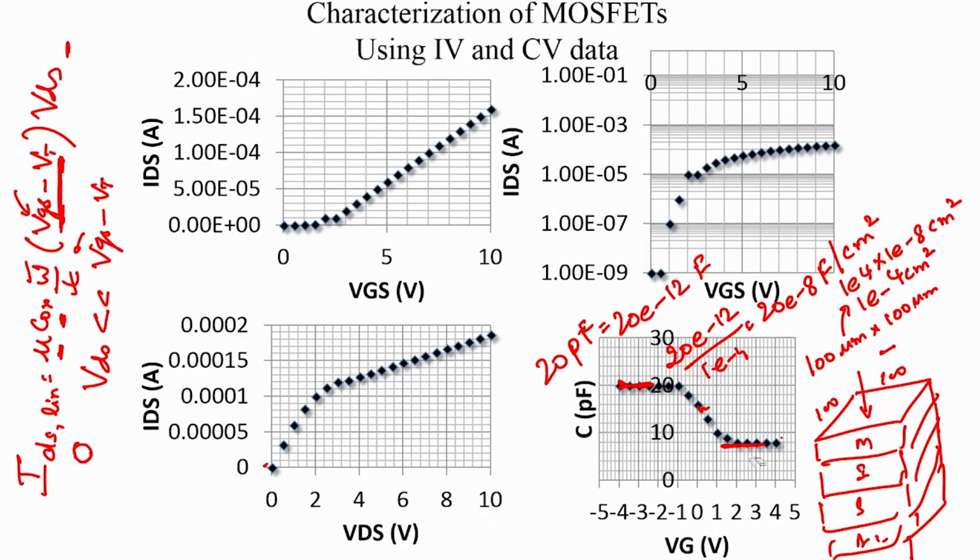Okay. So do forgive me if I am making typos here, but I think it is right. So this is about 200 nanofarads. So I think when we had the discussion on CV measurement earlier, I made a mistake. It was one order lesser, but what this tells you is Cox is 200 nanofarad per centimeter square. So now let us come to the slope.